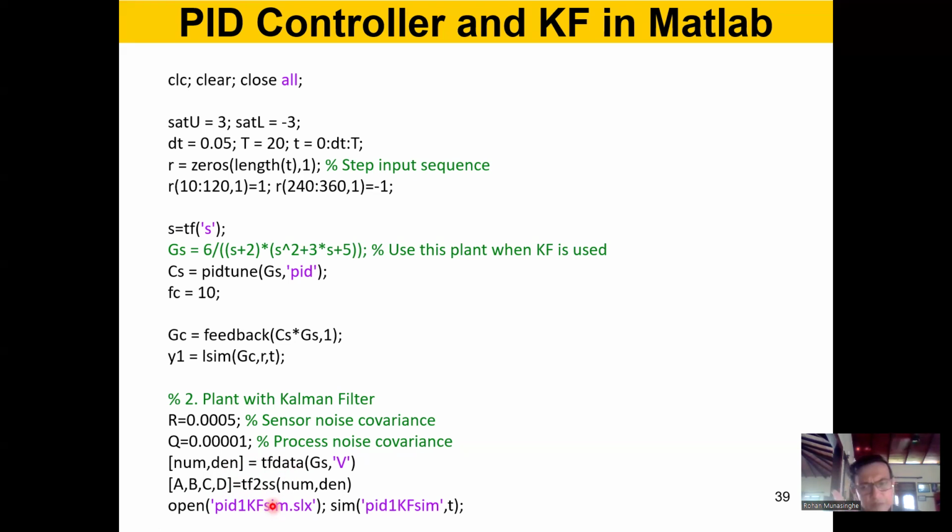When you run, you might run into problems also, right? For example, the Simulink block that I've given you is on the 2022A version. I think it's 10.4 something, right? But if you have an older version, it might give you a warning or an error, but it'll tell you what you need to do. You have to open the Simulink block in that version and then save it on a different version, and then you can put it back in the folder and run it. Okay, so you can do all kinds of things. All right. So all the best for your tests here with the codes. Please make sure you spend a decent amount of time with these MATLAB codes.